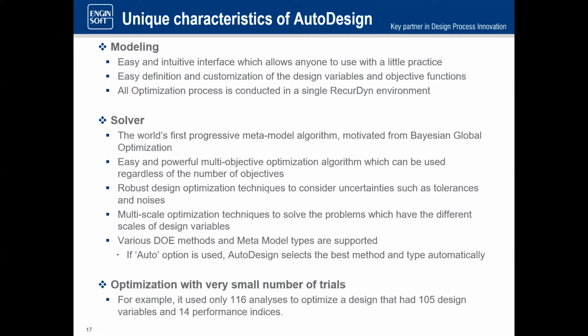And I redid it with AutoDesign, and I did an initial DOE of maybe 25 runs, or maybe only 9 runs. Anyway, I think I did 9 runs, and then when I went to do the overall optimization, it converged, I think, with 1 more run. So it was like 10 runs rather than 800.